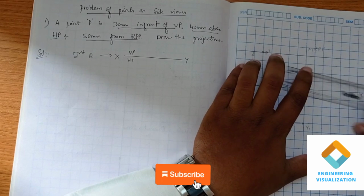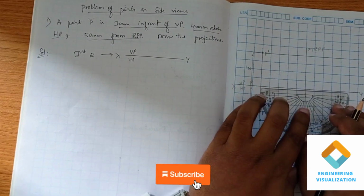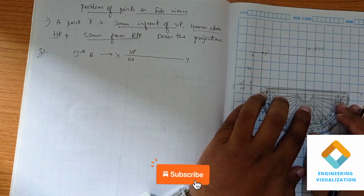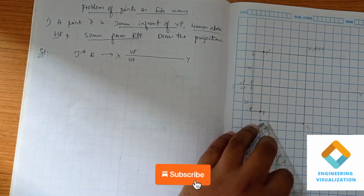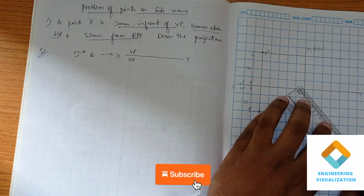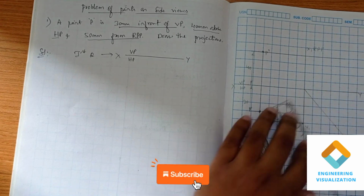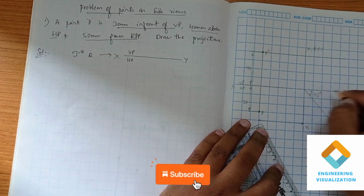Okay, now we know that the side view will be adjacent to this front view. So we draw a straight line. After this we have to draw a 45-degree angle line here, in order to connect the top view with the side view. So that is 0, 10, 20, 30, 40, 45. So mark a point, then draw a straight line. This is your angle line, that is the 45-degree angle line.